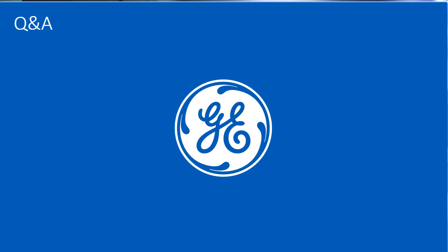You can do this with ESD mats. These are plastic mats, standard equipment that you roll out on the floor. But if you have larger facilities like storage facilities, it maybe makes sense to put an ESD surface coating there, or in laboratory environments as well. Then it makes sense to do it, because it's more cost effective, and also from the maintenance point of view, it's easier to do so.